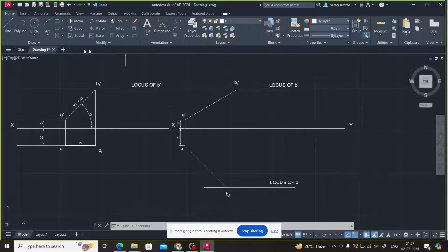Yes, sir. Okay. Now I wanted to draw one vertical line from B1 dash. Switch on the ortho mode. Now till how much length should I draw this line? I wanted to draw the vertical line from B1 dash. Look very carefully. I am just moving very close to A now, not clicking anywhere. Can you spot the green colored dotted line? Yes, sir.